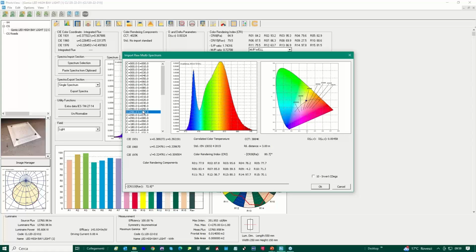and it is very useful because through this analysis, you can see if there is a color shift between, for example, gamma 0 degrees up to 90 degrees. Sometimes the lenses, sometimes the glass, sometimes the luminaire itself affects the light emission. So it switches from one color, for example the color you may have at gamma 0, to gamma 75, gamma 80, where it may shift to yellow.